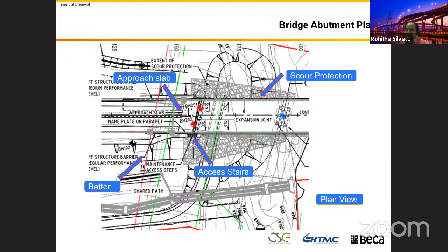So when you are in good ground, your approach bridge is very standard. In Australia, most of the places we use 6 meters. And you can see we have a batter around because of this level difference in your road surfaces, if you have the space, you can batter that. The batter is 2 to 1. That means if the level difference is 4 meters, you need an additional 2 to 1 batter, meaning 4 meters height. The horizontal dimension you need is 8 meters.